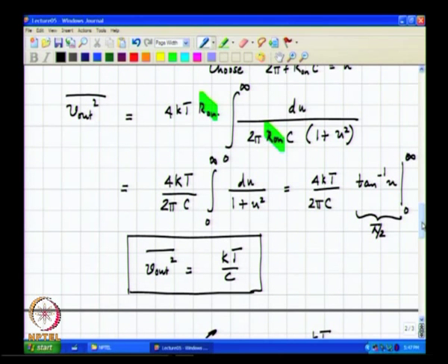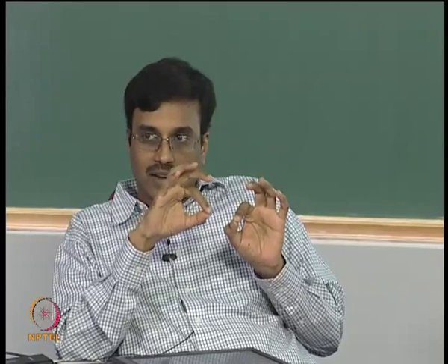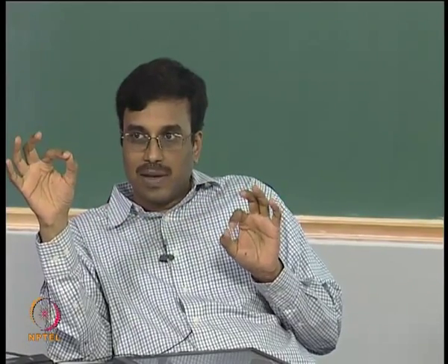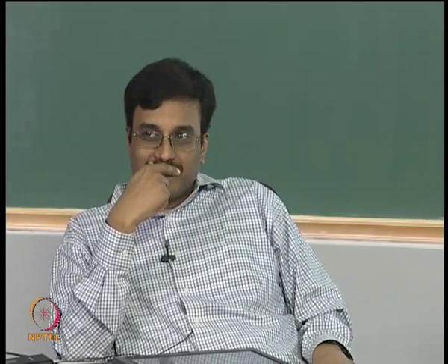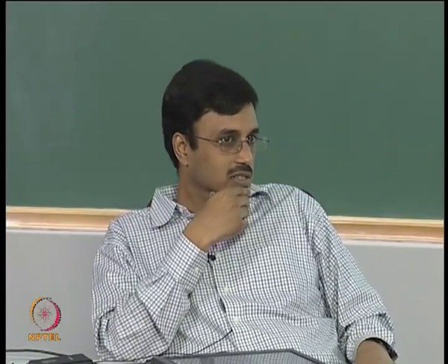Yeah, but clearly the final expression for noise has temperature in it. That we have taken when the switch is open. So any R is not a good argument, but please note that the value we are sampling, which is held on the capacitor, has something to do with the resistor, is it not? So, why do you think this makes sense? Impedance of the R is constant with the frequency. So, what?